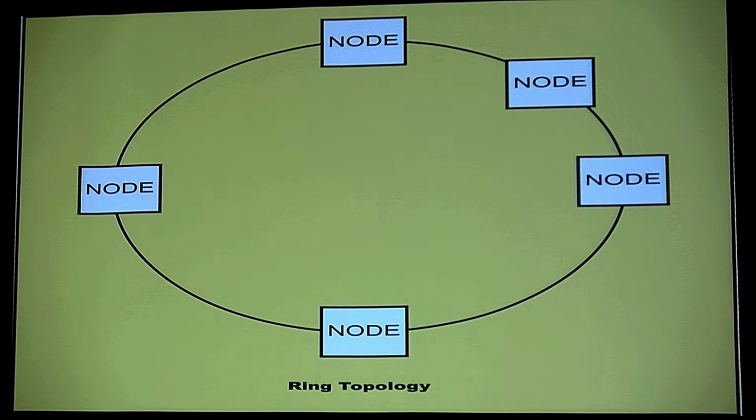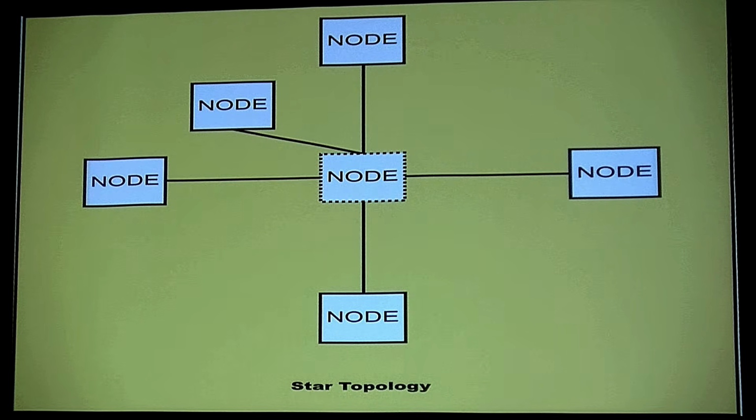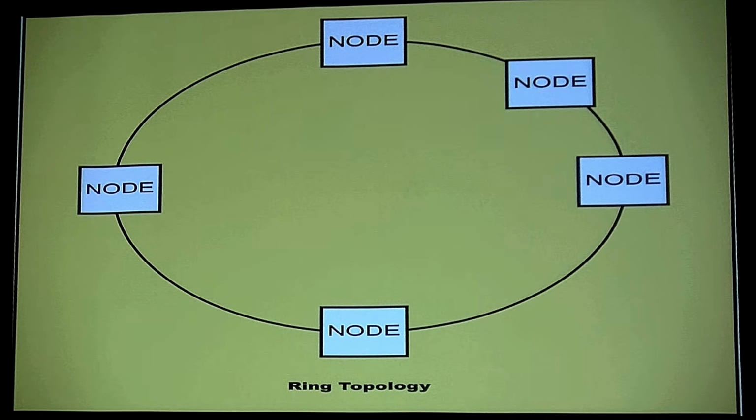The other thing that I didn't tell you is, if I lose my master, if we have a master, the whole system is down. So this is not the best system if I'm looking for robustness, right? Because if I lost one module, the whole system goes down. That's very much like this system. If I've got one ring and I ground the ring, the whole system is down.